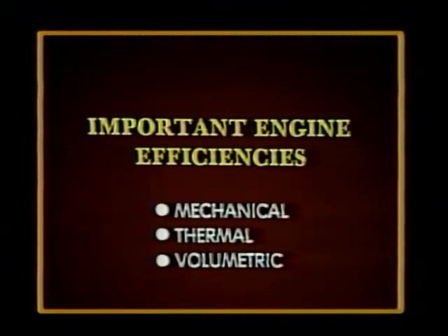In order to measure the performance of an engine, we need to look at some of its efficiencies. In this way, we can compare one engine or one type of engine with another. There are 3 main efficiencies to understand. These are mechanical, thermal, and volumetric efficiency.